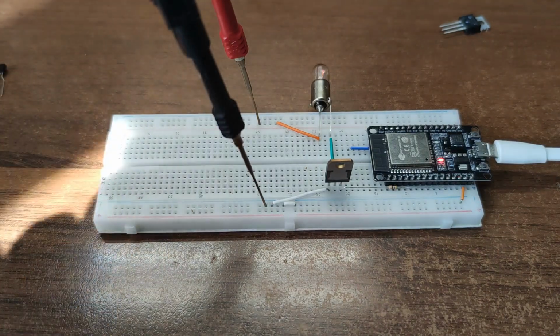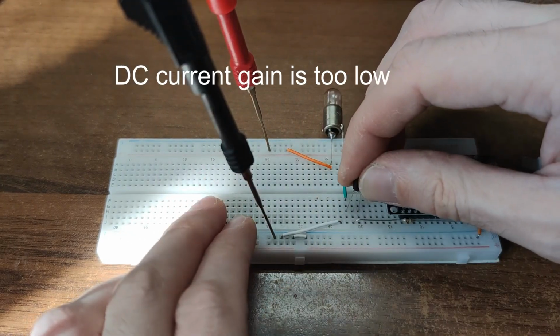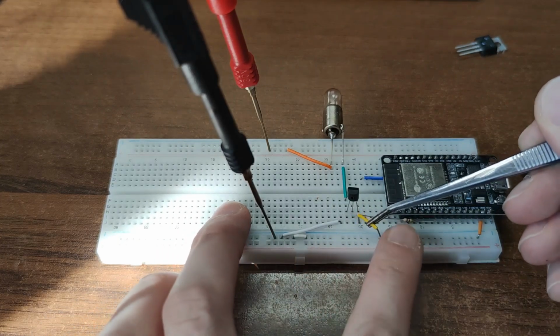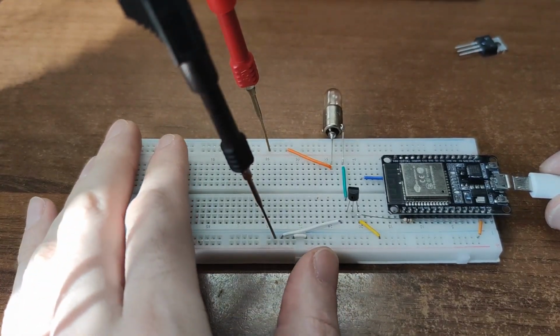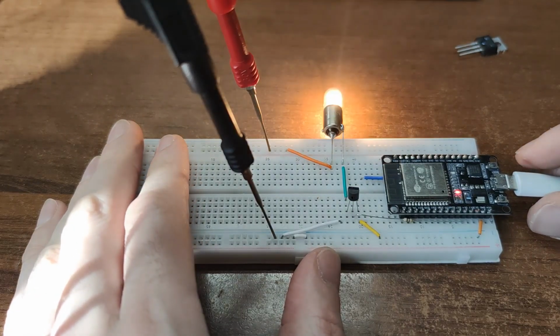The lamp is dim because the transistor is not fully open. Let's fix it by reducing the base resistor value. I'll explain that later in this video. Here it is. The circuit works in reality.